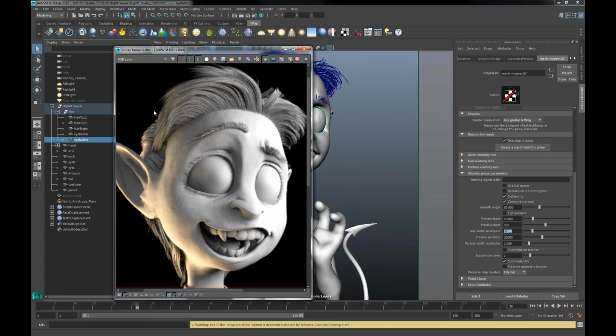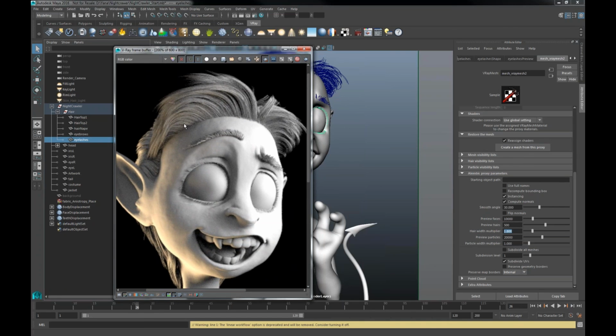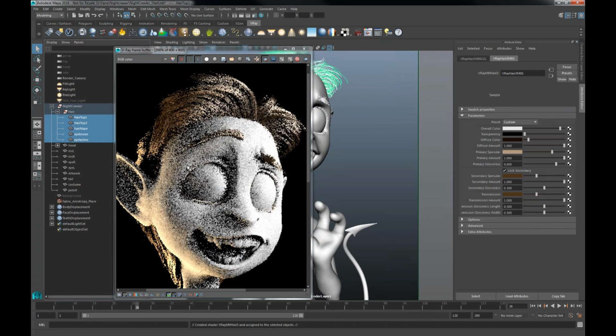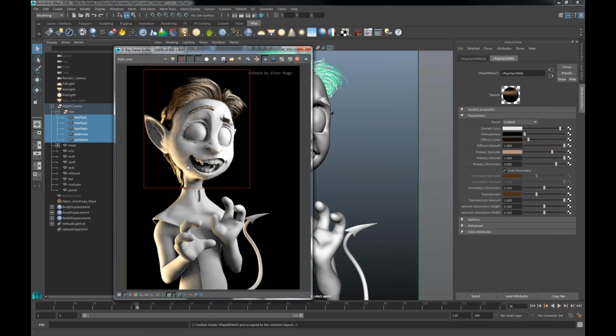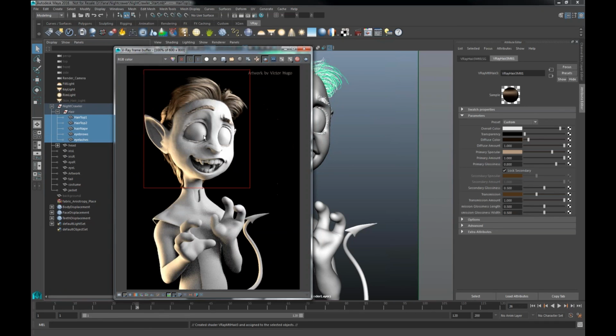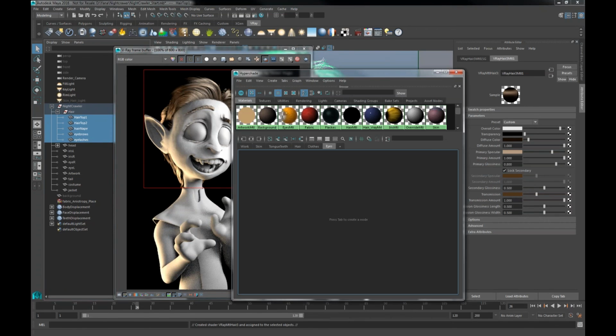But we can optimize the rendering process, and this is by using the V-Ray hair material. And I'm going to assign one from our shelf just by right-click on the mouse button, and here V-Ray hair material. So here it is. And by using the V-Ray hair material, V-Ray will consider that those are not tubes, but those are like stripes, and there are polygons which are facing the camera. And since the hair is really, really thin, you won't be able to see any difference.